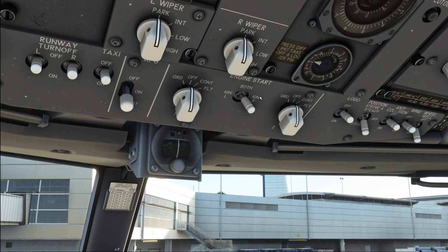The reason is the right igniter runs off the electrical standby system, and therefore the engine start later on is a good test for the standby electrical system. If you are operating on an unmanned station, so where there is no maintenance available, then you would use the left ignition switch.